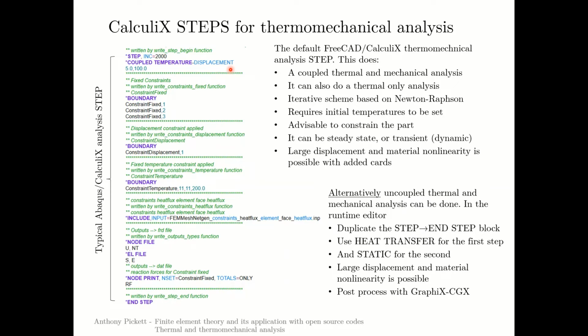If you haven't got any mechanical boundary conditions or mechanical loads, it will also do a standard thermal analysis, but it will use this iterative scheme. I've listed a few points here regarding this particular analysis. As I say here, it's coupled, thermal and mechanical within one step.